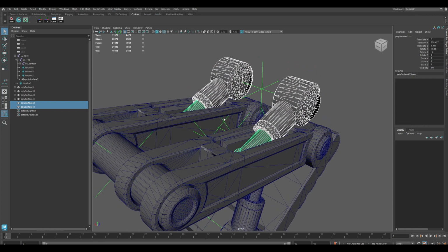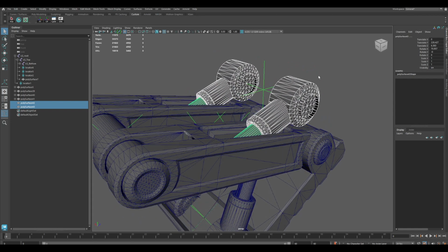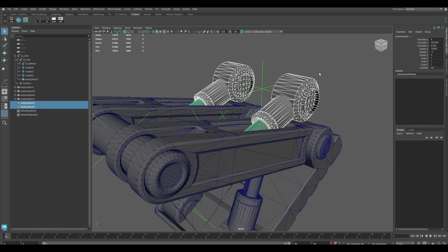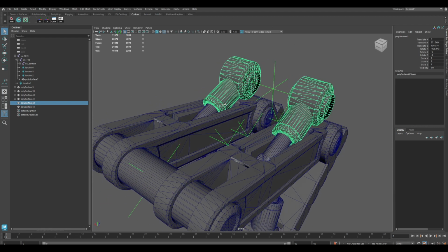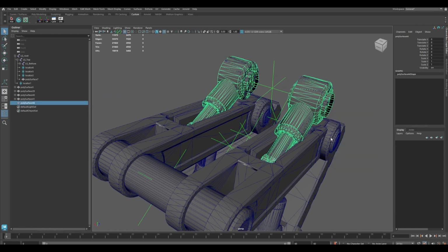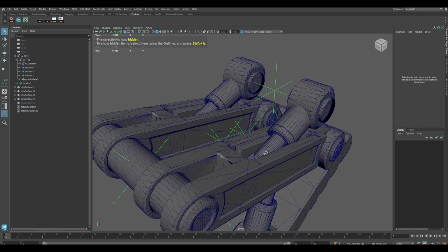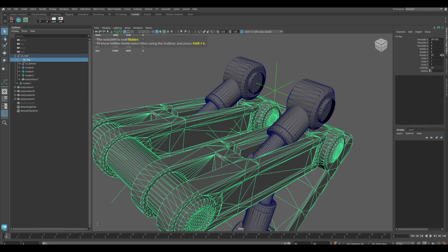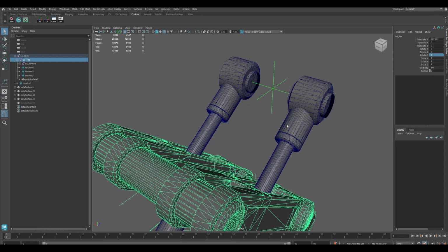The order that you select your parts when combining is important, because for the morph target to work properly, you need to have all your vertex information the same for each object. So make sure that you always select them in the same way. So select the top, select the bottom, then combine them, then delete the history, and I'll hide it for now. Let's return to the 0.